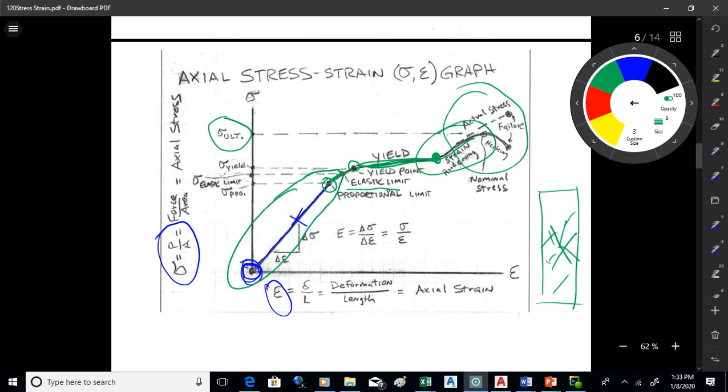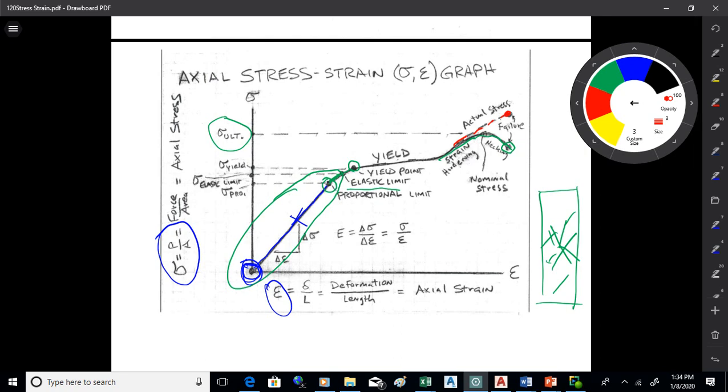Now one thing that's happening here, if you look at this graph, is you see this strain hardening starts to go up, and then it tails off at the end. The reason for that is the necking. See, if you want the actual stress, which I'll put in a dashed red line here, that will always increase until failure occurs. But the problem there is finding the stress depends on the cross-sectional area. And it's hard to track the true cross-sectional area of the sample when it starts to neck.